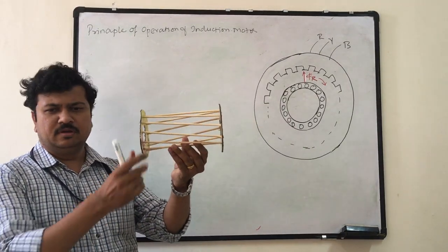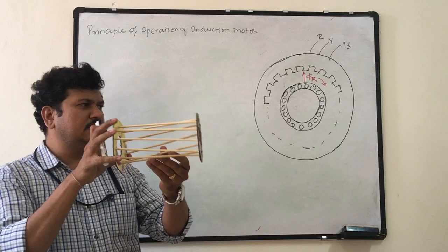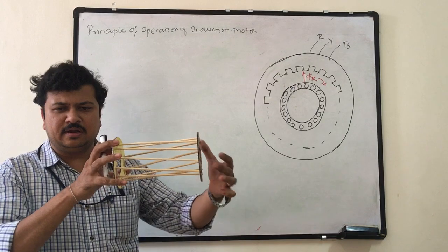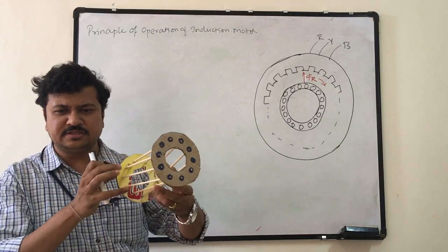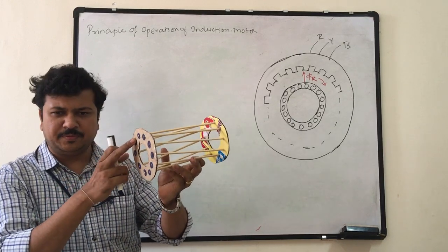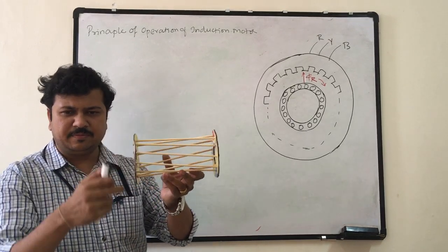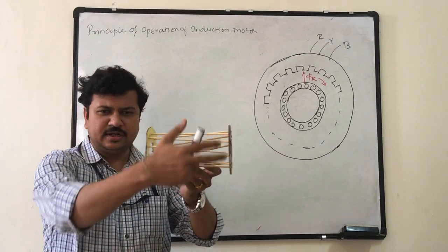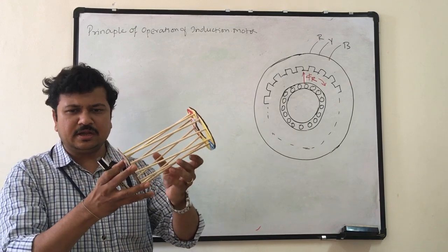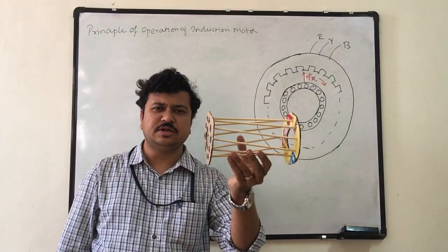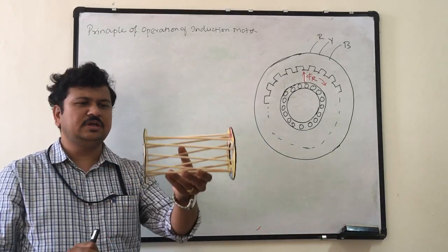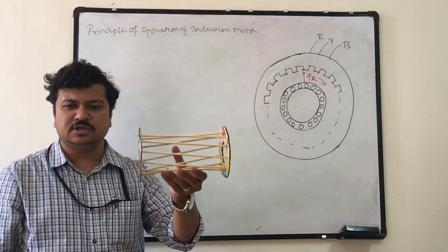We know that these are the conductors and these are the end rings. So when these conductors are brazed at the end rings, this is forming a short circuit structure. Conductors or bars are made up of copper. So do you think that this is an entire short circuit? Definitely, it is a short circuit condition. Electrically this rotor is under short circuit condition, and these conductors are placed inside the slots and the slots are covered. So this is an internal skeleton of the cage rotor.